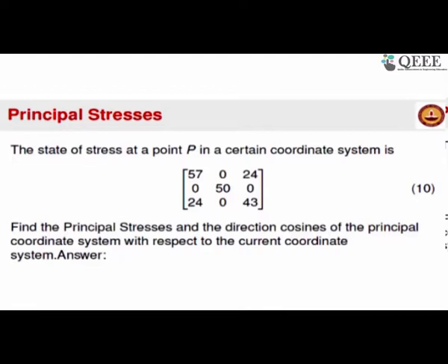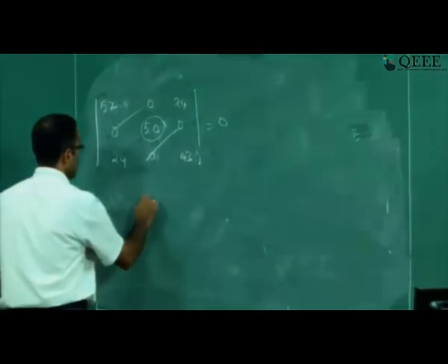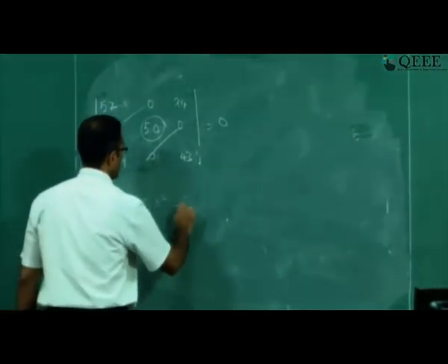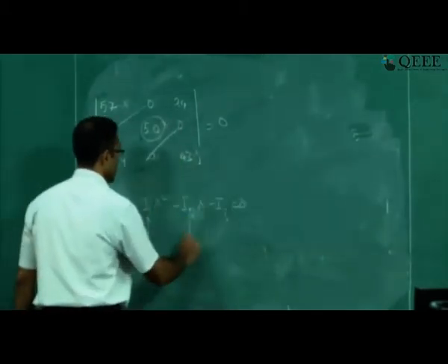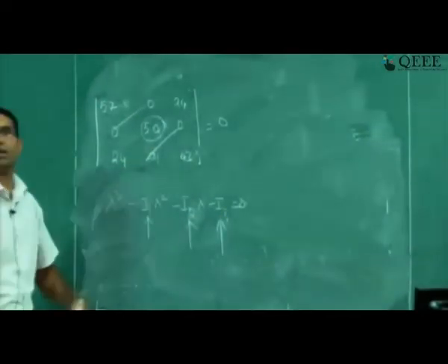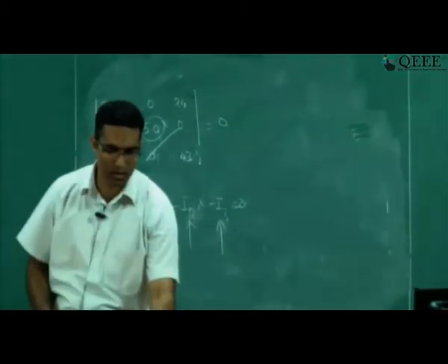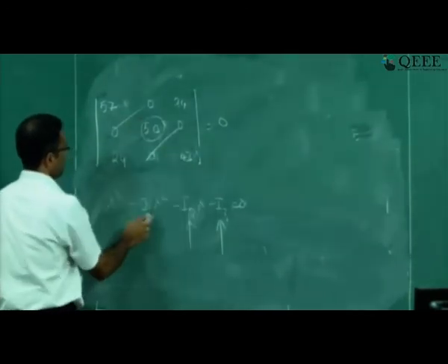when we have to find out the principal stress, we can adopt two strategies. One is simply put minus lambda to the diagonal components, take the determinant equal to 0 and solve that cubic equation. Or you can simply write down the characteristic equation, where each of these things are invariants, so you can easily calculate them from the stress tensor, write it down and then solve this equation. Both are basically equivalent methods. It's just that one of the methods might save you a little bit of time in trying to find this out.